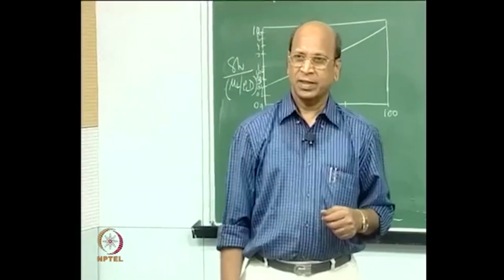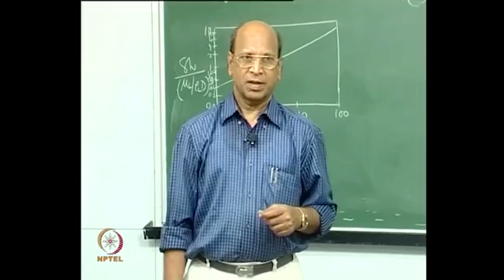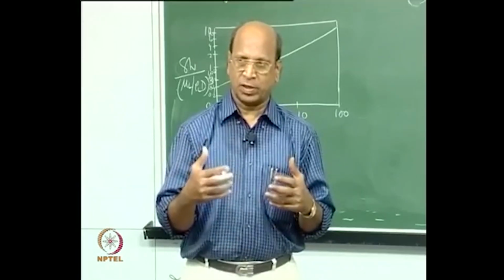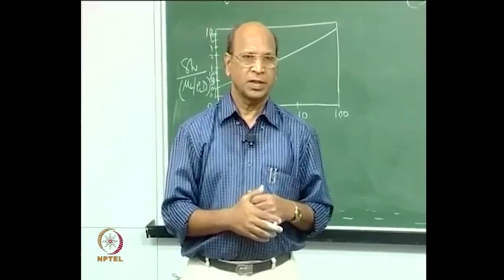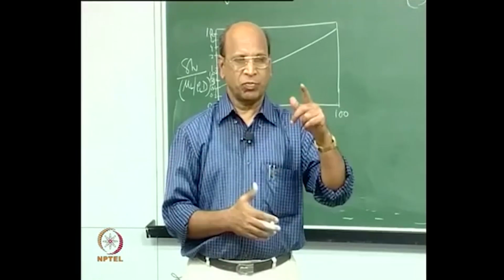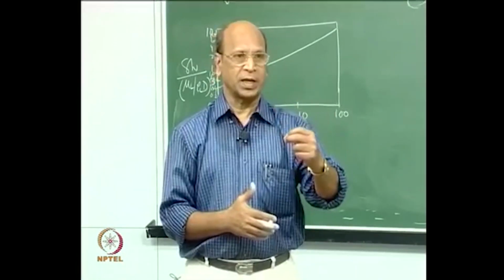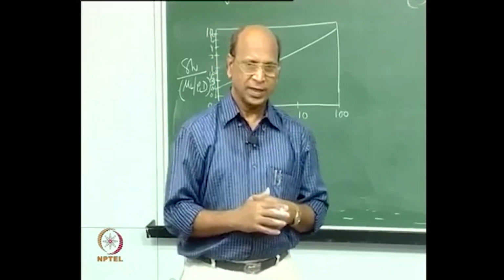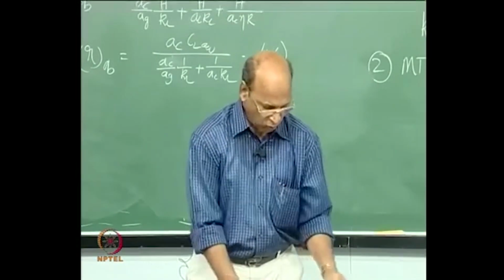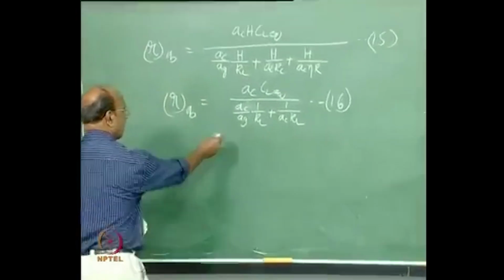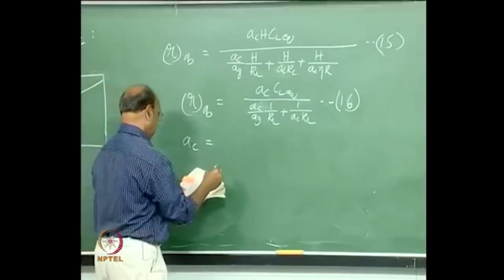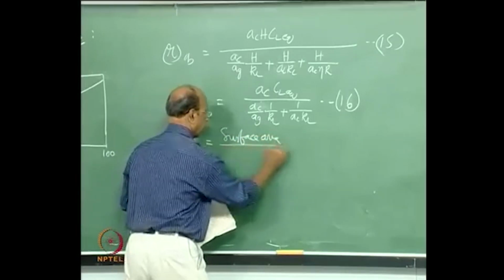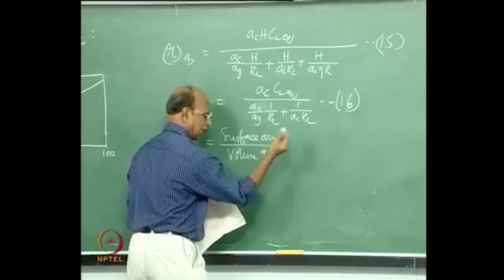Okay. Do you know how you find that? If I want you to develop an equation for that, AC is the external surface area per unit volume of the particle multiplied by the volume of the particle and divided by the volume of the slurry. Okay. Anyway, I think you would not have got that, but I will tell you, because that is also how you find out AC. Then we can discuss that. AC is surface area per unit volume of bubble free slurry. Okay. So, surface area per unit volume of slurry liquid. Okay. Liquid I am writing.